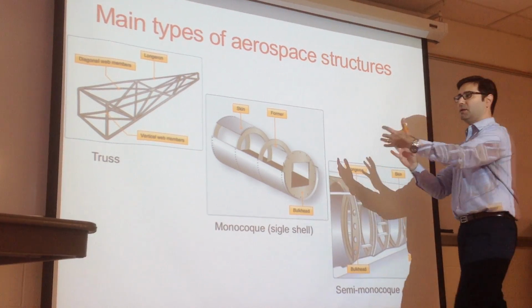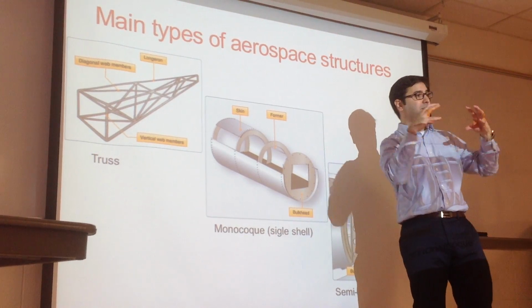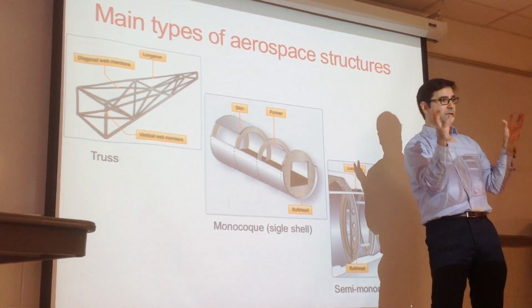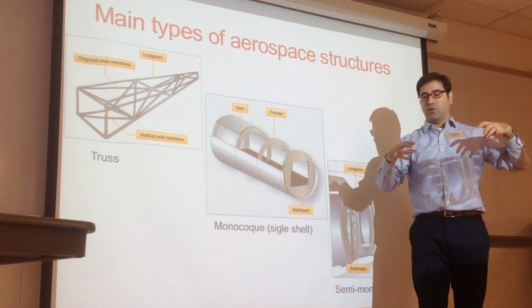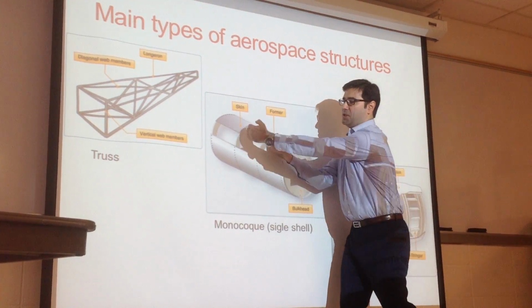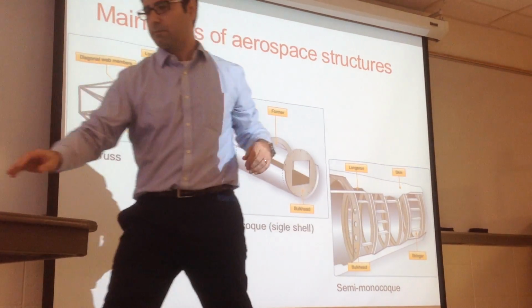Because what happens, let's think that now this is a fuselage and you're maneuvering your plane, so we have some bending itself. It's probably the tail is pushing one way, the wings are pushing another way, so this may tend to bend. So the parts that are under compression, now just imagine you have a thin sheet, and now this distance is becoming larger and larger.